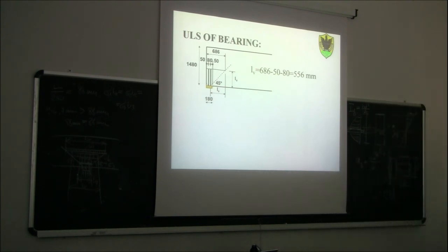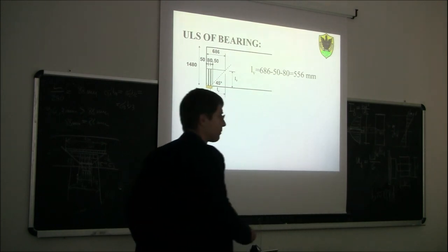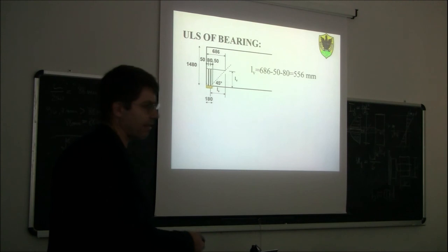So basically the idea is that the screws are going to transfer all this restraint reaction within the wood, and they should be as long as the length needed in order to reach the breadth here of 686 millimeters at the end of the point of the screw. Okay? It's quite simple. It's a kind of geometrical relationship.